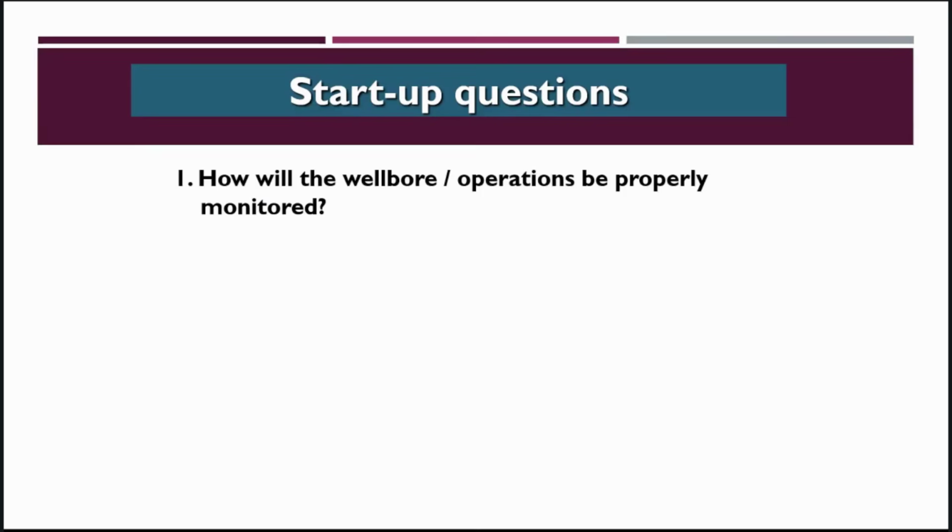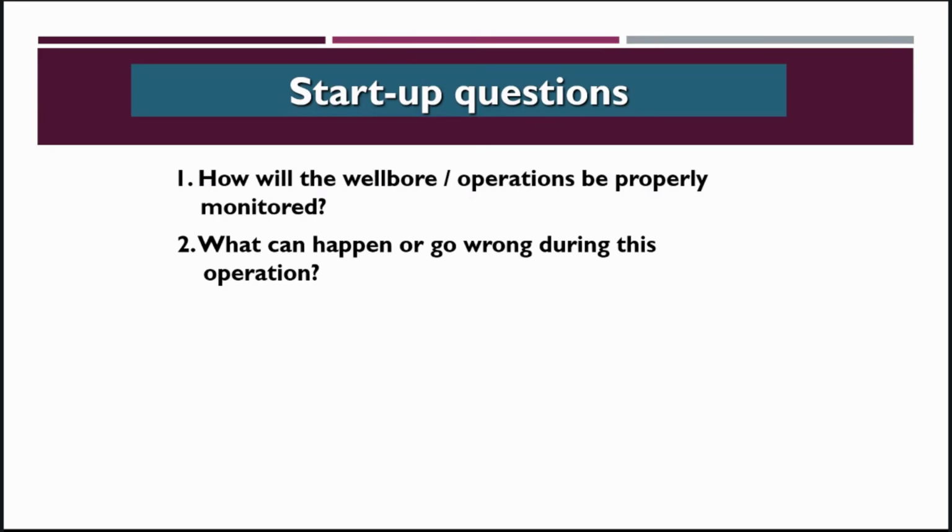So before starting any job, you should know how the wellbore operation will be properly monitored. You should ask yourself how I will properly monitor the operations. Then, what will happen if something goes wrong? It means, do you have a backup plan or not? If this equipment fails or if this procedure fails, do I have a backup? Before startup only, you should have answers to these questions.